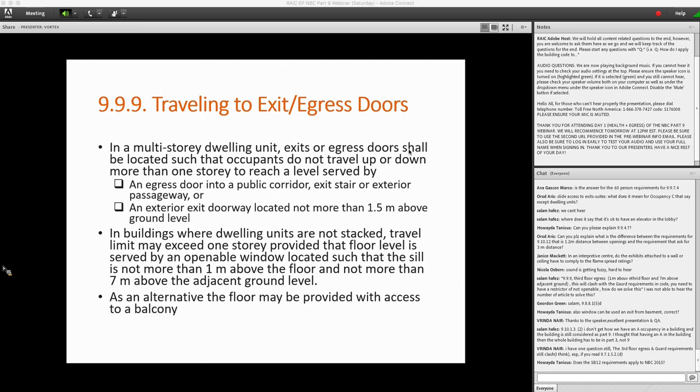So 9.9.4.7, stairways in two-story Group D or E buildings. I believe I already went over this, but it's typically applicable if you have a two-story building or suite that is either Group D offices or Group E mercantile. If you meet any of these provisions under 9.9.4.7, which is that, first of all, the building is 2 stories, and the area occupied by the suite is not greater than 100 square meters per story. So you can have only 100 square meters per story in the 2-story building.